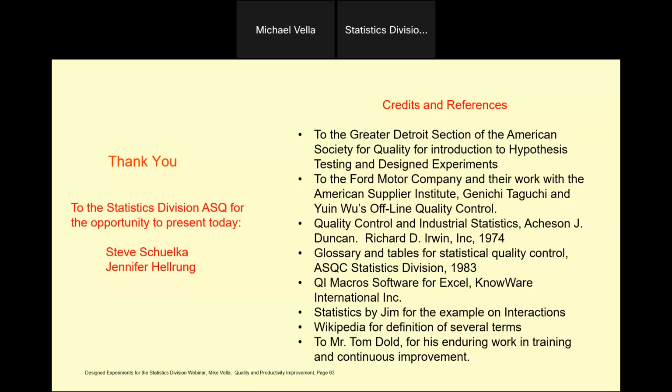Here's another question. What are the barriers you see when trying to use design of experiments in industry, just in general? Well, they're not cheap to do. Oftentimes it takes time to set up production and do the changeovers, and so that's the whole point of using fractional factorial experiments. You can test as many as 7 variables in 8 trials.